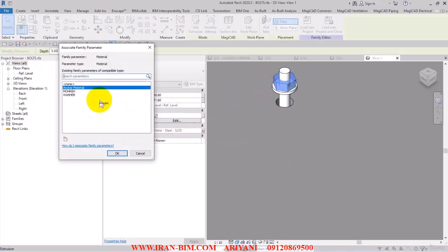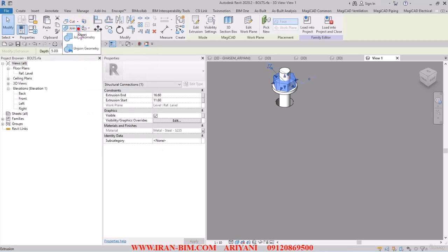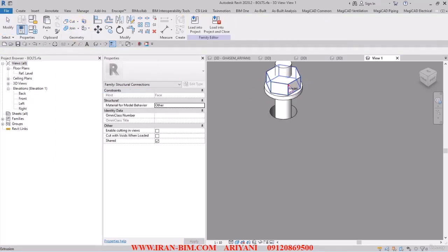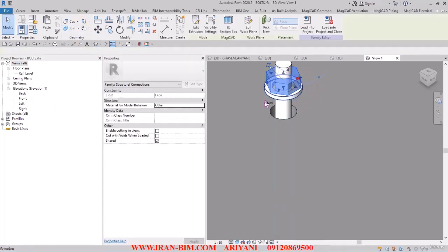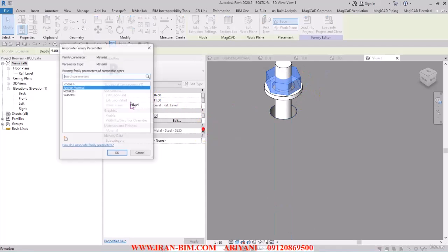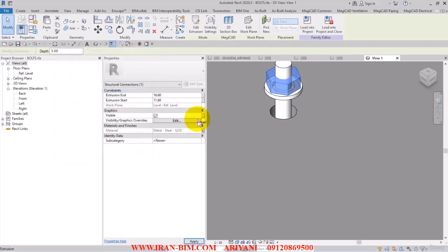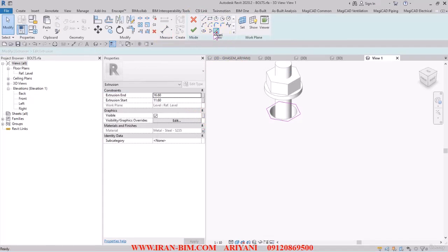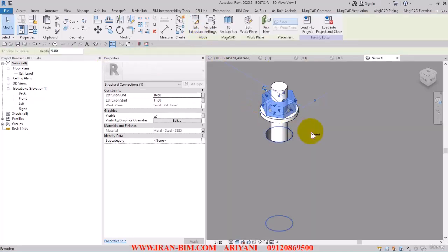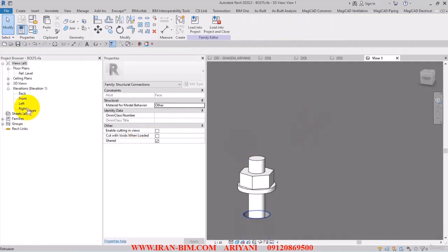Then click OK. Now, because this part has been joined, the changes don't really apply. So I go here and unjoin the geometry, then select this one and put it under nut. Then open up the edit and select pick. Then select the offset and put in 1/100th of a millimeter, which is for the groove that we have here, and it looks like this.